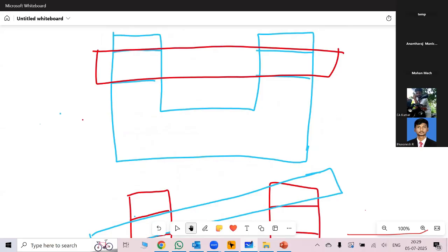In the drawing, the threaded hole has an MMC callout. During inspection, some inspectors apply MMC, some inspectors do not. Which one is correct? Inspection method. MMC is not given by the inspector, MMC is given by the designer. Whenever the designer gives MMC in a drawing, there is some extra tolerance available for the manufacturer and for the inspector. So they have to utilize that extra tolerance for manufacturing and inspection.